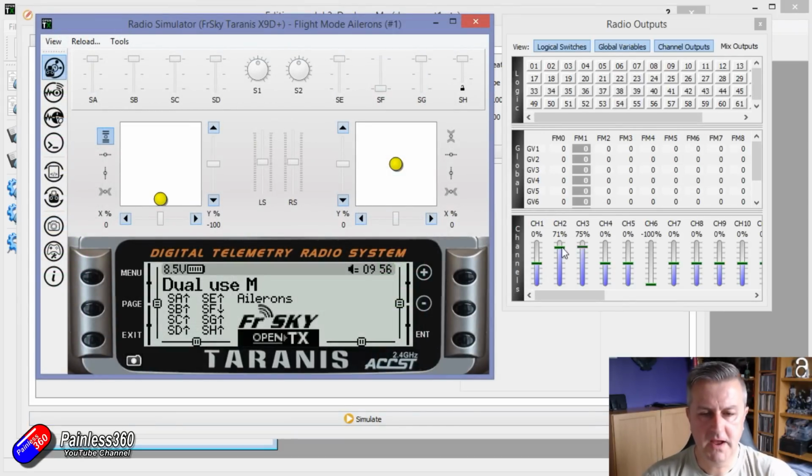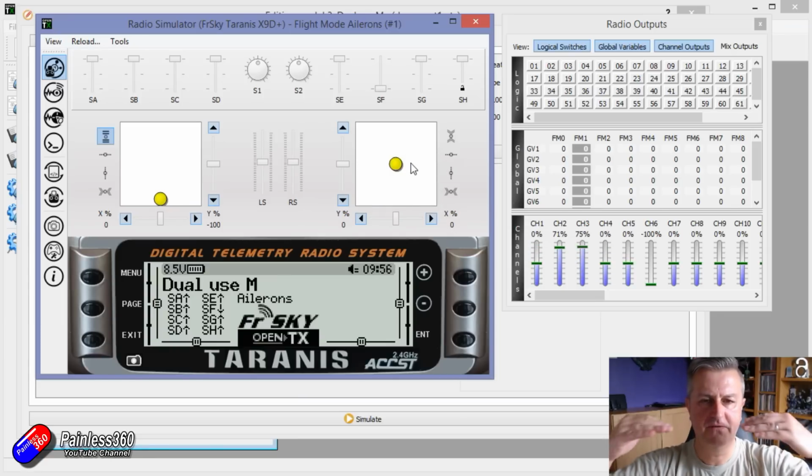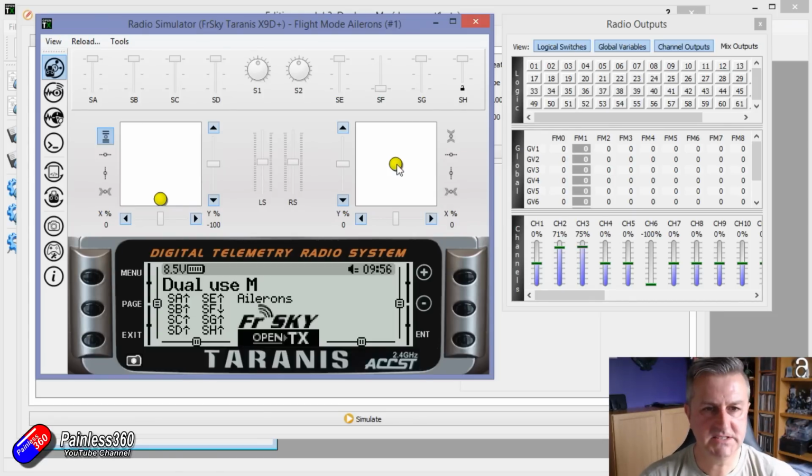So now if we simulate it, you'll see that the flaps don't go all the way to the top, and that might be the position where we're actually in line with the wing, and when we move them they only move the extent that we have set up with those curves, and curves gives you much more fine control, particularly as you probably don't want the flap, because hopefully you can see here that it means using a curve, the flap will never try and rise past the most upward point and damage the linkages.